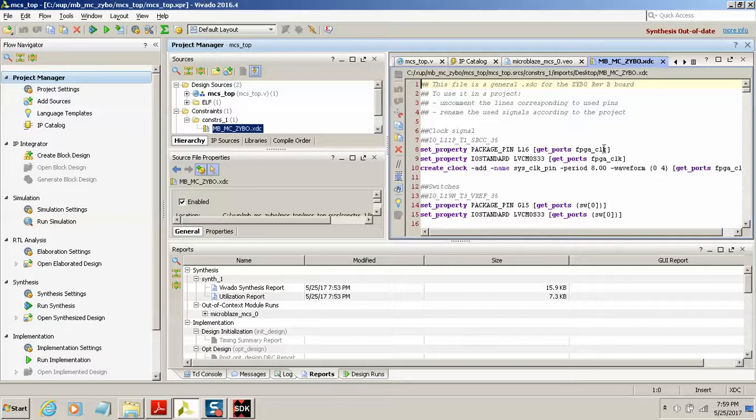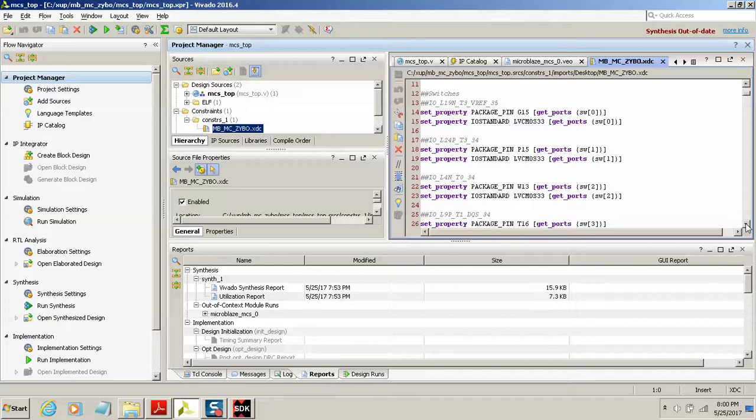Where it had the clock, I inserted the project clock, which was called FPGA_clock. It needed to go into two different sites. The waveform for the clock is for 125 megahertz with a cycle of 8 nanoseconds, half on and half off, as shown here. Then I've got my input ports on switch 0 through switch 3.